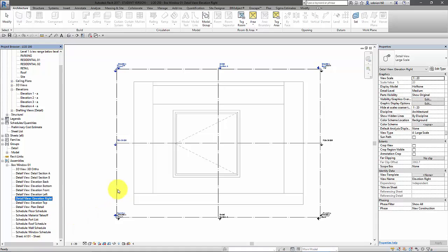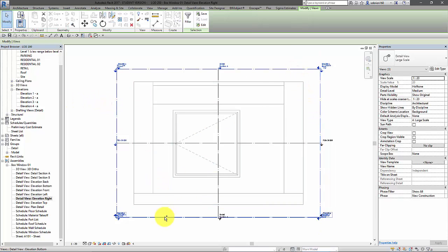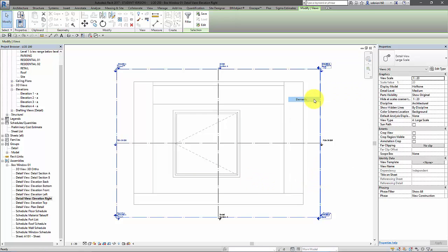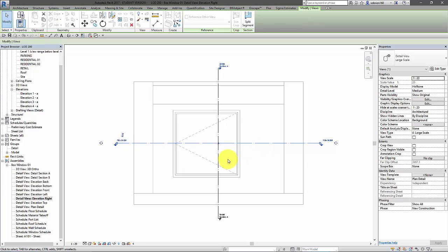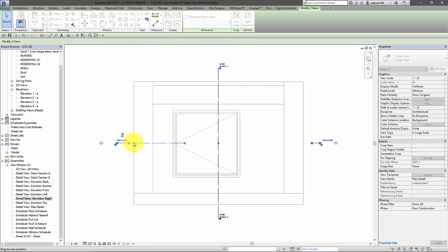So what I can do then, I can edit this. For example, it always does an enormous amount of elevation lines. So I can go around here and say, well, I don't need to show where the plan views are coming from. So I'm just going to click those and hide them in the view elements. And then we can break these sectional views just so it makes it graphically a bit stronger on the page here, because otherwise you're overwhelmed with lines and information.